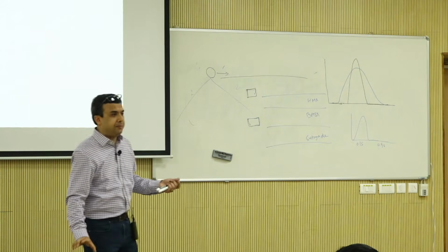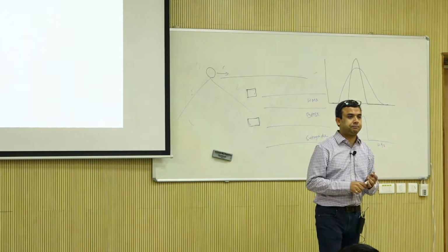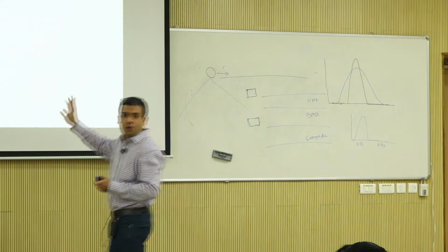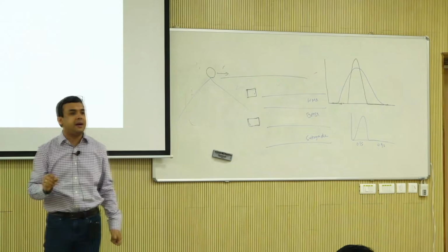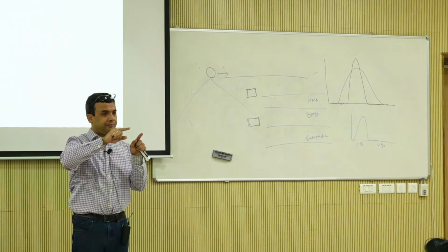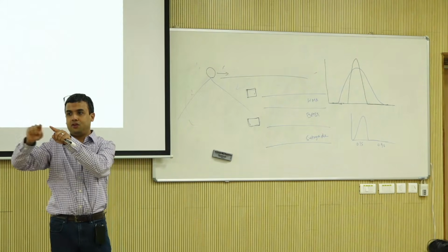Yeah, there is a gap between the load, vehicles and stuff, right? So rapidly applied loads. What is rapidly applied? 0.1 second is the load pulse, 0.9 second rest, then 0.1 second, 0.9 second.